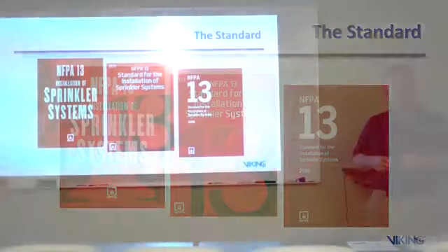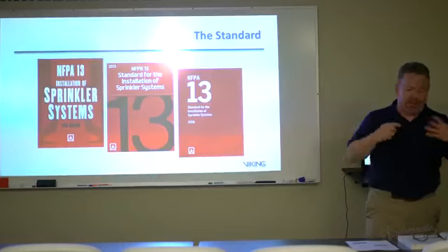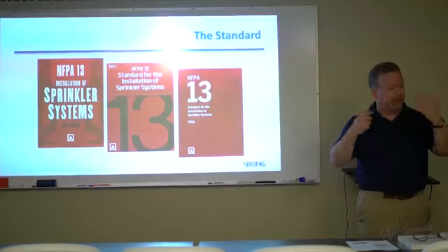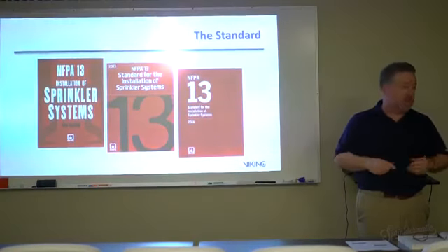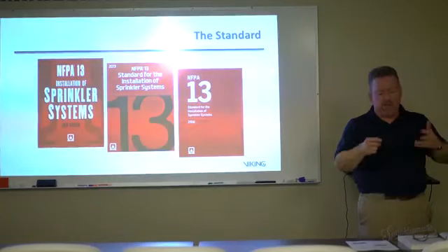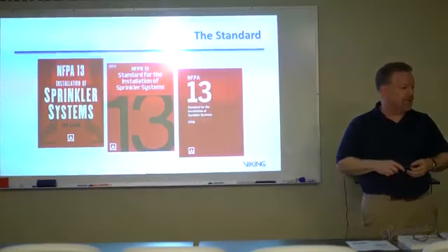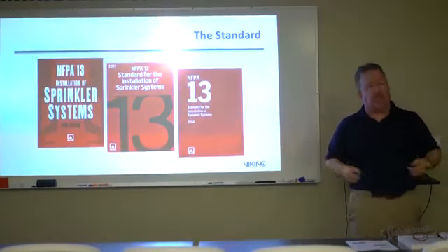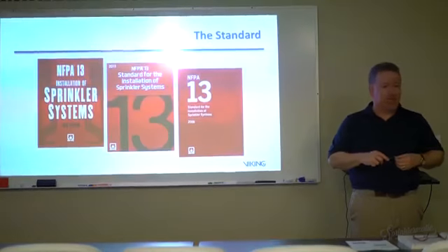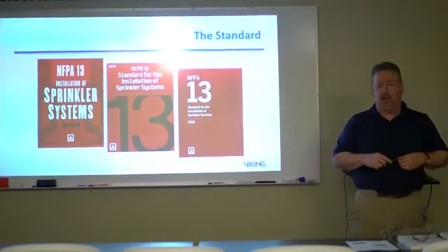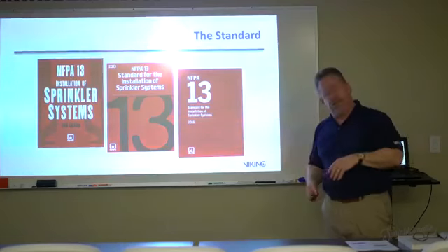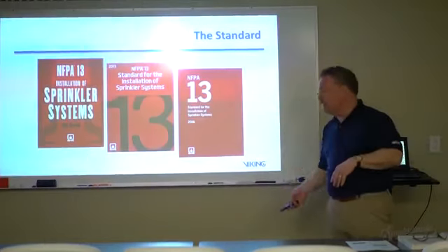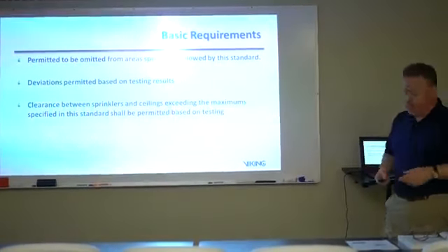It's been around for over 100 years. It's been changing every 3 years, so the requirements in NFPA 13 kind of flip around. Every now and again you'll change some pretty significant ones. As I said in the previous session, we talked about the one in 2001 that said all light hazard occupancies will now have quick response sprinklers in them. That was a big change in the document, and since then we've been working with that kind of rule. Every 3 years it gets changed.